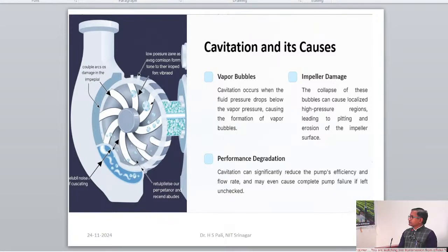As we slowly rotate the pump towards the vertical position, we see the flow rate decreases but the pressure increases. That's because it's now pushing against the water and the friction. As we get all the way to the vertical position, there is zero water flowing out of the pump but maximum pressure, because it's using all its energy. So if you are using the maximum head, what condition arises? The pump is working but water will not come out. No discharge will take place.